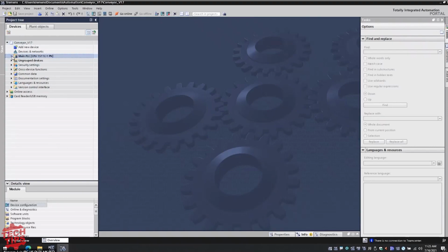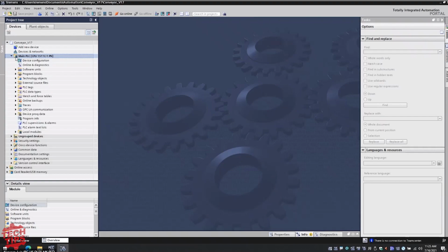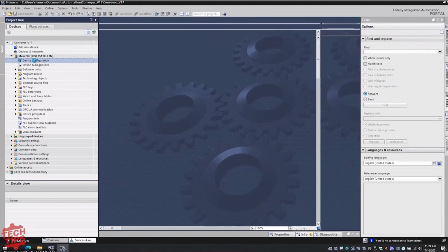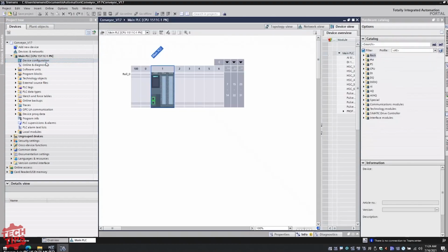Exactly. So the way our hardware works, there's no firmware required per the version of software you're using. For any users who upgrade their TIA Portal license to version 17 and want to upgrade all their machinery or equipment to version 17, they can easily do that using the process I just showed you, and download to that version 17 project, and nothing changes. The program blocks, everything is exactly the same as it was before, even the older firmware. So the firmware does not change in the project, and you're not forced to change firmware.